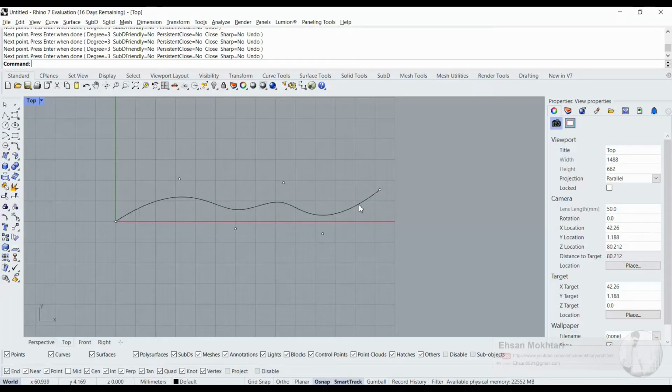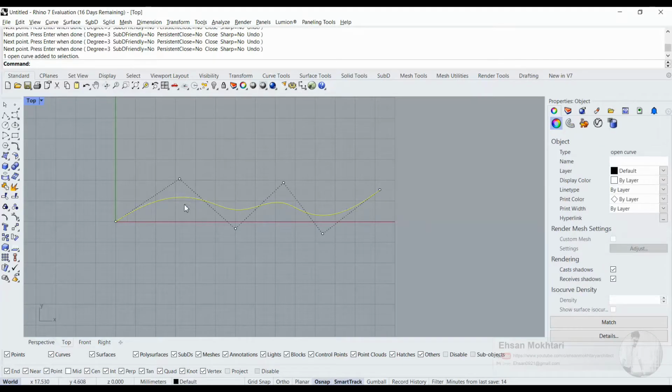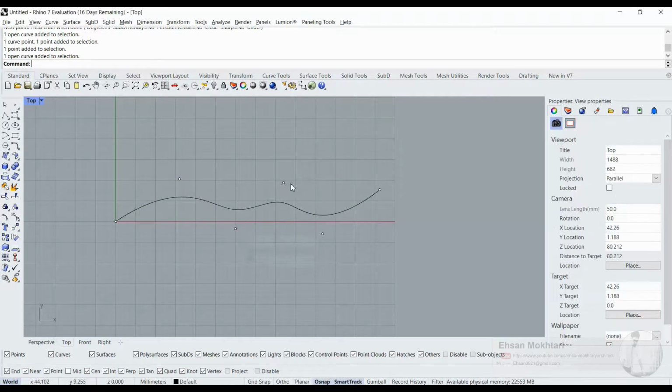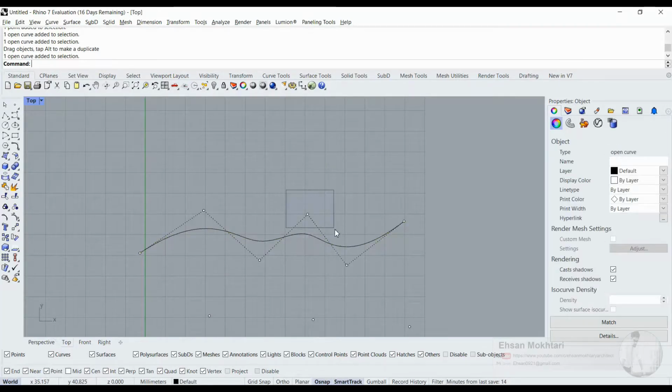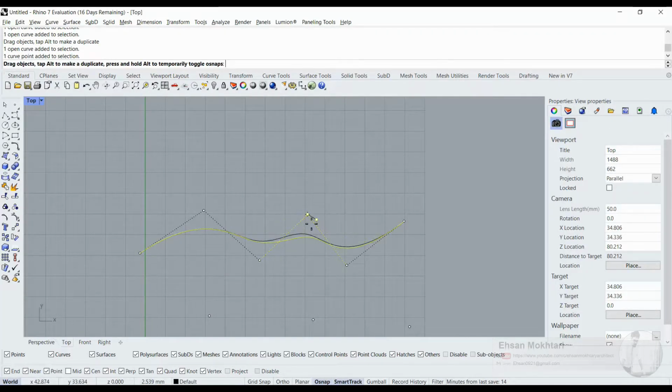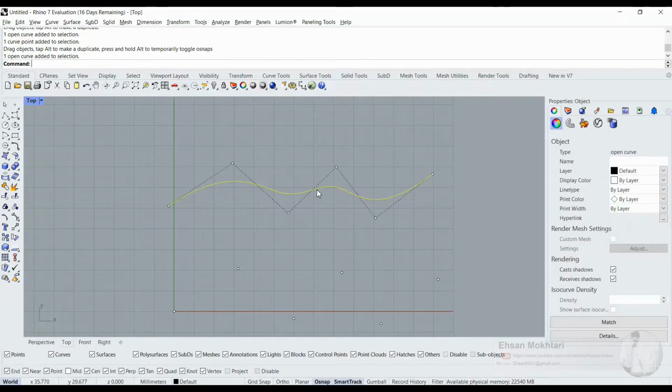As you can see, for control point curve, when you select a point, it doesn't mean that your curve is passing through that point. It means that point is the control point of the curve. You see, they are the control points of each curve. If I drag it here, you can even modify it, but this control point is not on the curve, it is actually for controlling.